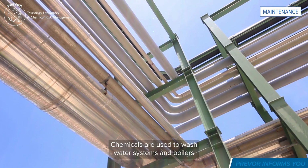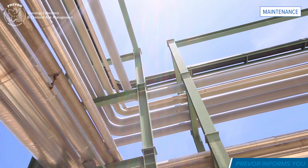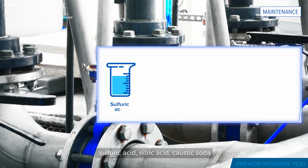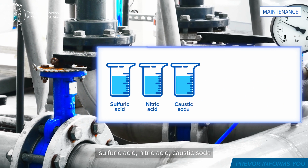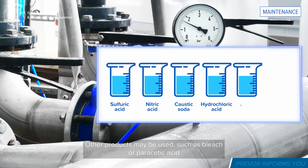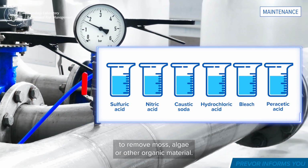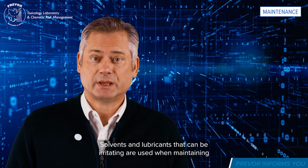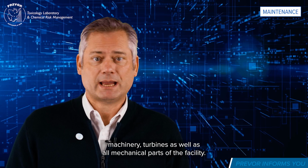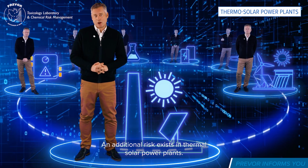Chemicals are used to wash water systems and boilers that contain impurities such as copper, iron or nickel. Chemicals used to remove mineral residues are mainly sulfuric acid, nitric acid, caustic soda and hydrochloric acid in large quantities. Other products may be used, such as bleach or peracetic acid, to remove moss, algae or other organic material. Solvents and lubricants that can be irritating are used when maintaining machinery, turbines, as well as all mechanical parts of the facility. An additional risk exists in thermo-solar power plants.